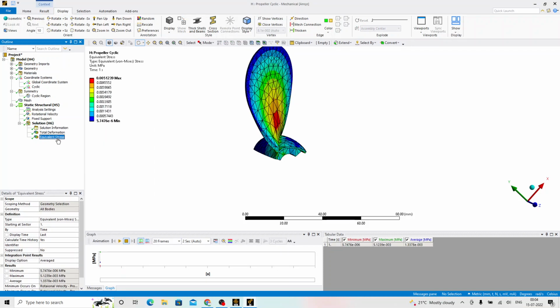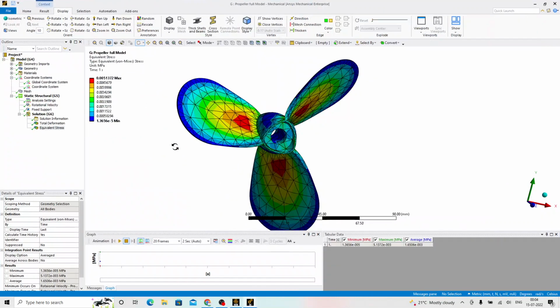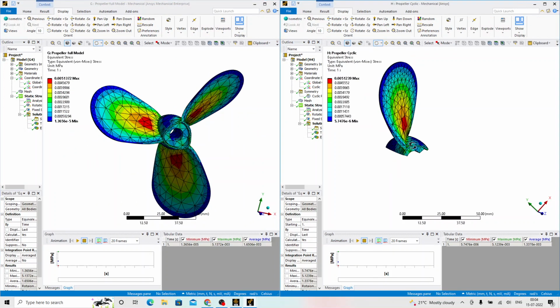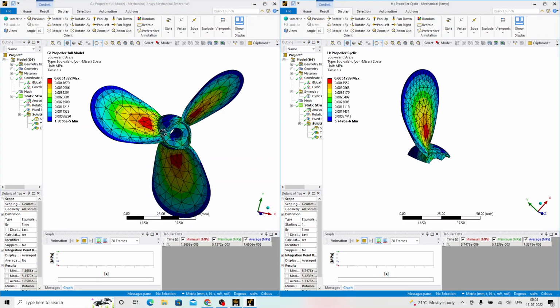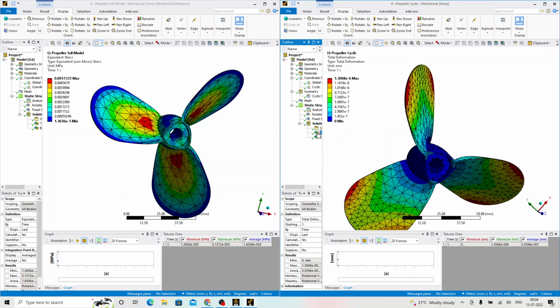What we learned in this analysis is even the 3D analysis can be simplified if at all there is a particular nature in the geometry. In this case, for 360-degree angle at 120 degree each of these blades are placed. So we can just consider only one blade if required, that can be expanded to the final model.